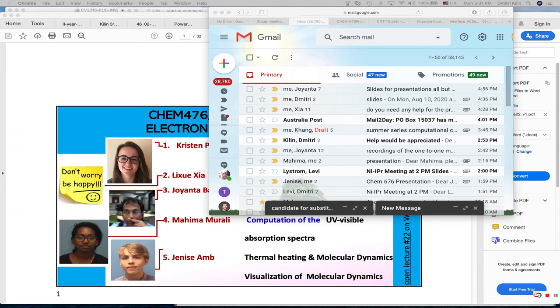The third part is the ionic relaxation, which controls the structure optimization. The first one is NSW, which controls the number of steps of the whole structural optimization. The second one I usually change is ISIF, which controls the stress and relaxation of the atoms and the whole structure.